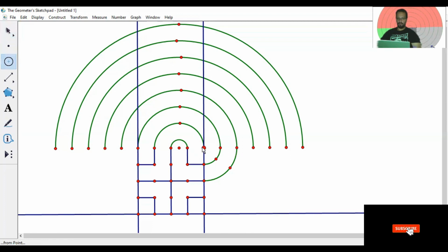Start at the top of the square from the upper right corner. Construct a circle to the next point. Click. Add a point to that circle. And then hide it using Control H, and then click 1, 2, 3. And construct an arc through 3 points.